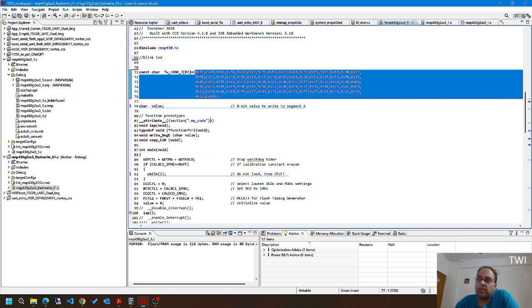Now after that, there is one more thing that you need to think about. As I told you, your execution code should start from D000, and your IAP code, which is going to program your flash with the new firmware, has to be located in a separate location, obviously, because if you are within the region of D000, you cannot overwrite the same region. So that is going to be written in the linker file.